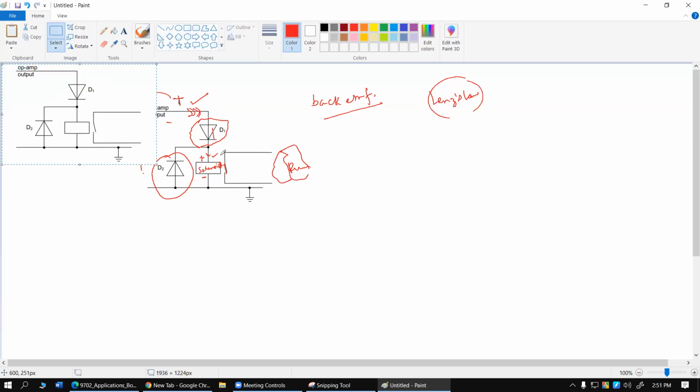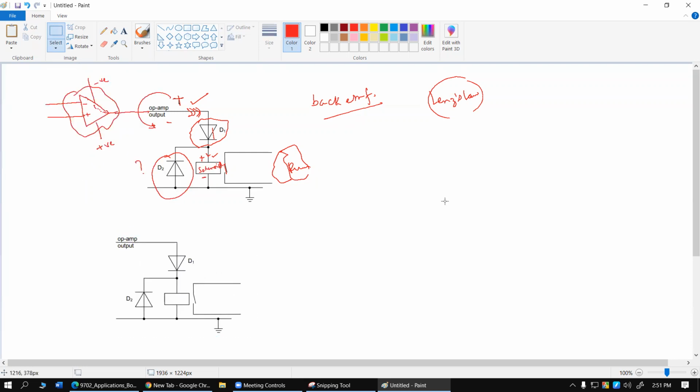That's where this additional D2 branch comes in. So let me just place the figure one more time. Now you should be able to see it a bit more clearly. So now have a look over here. I'm drawing in green. So whenever the solenoid produces its own high voltage, we produce an alternative path. So this could very well be only a single wire.